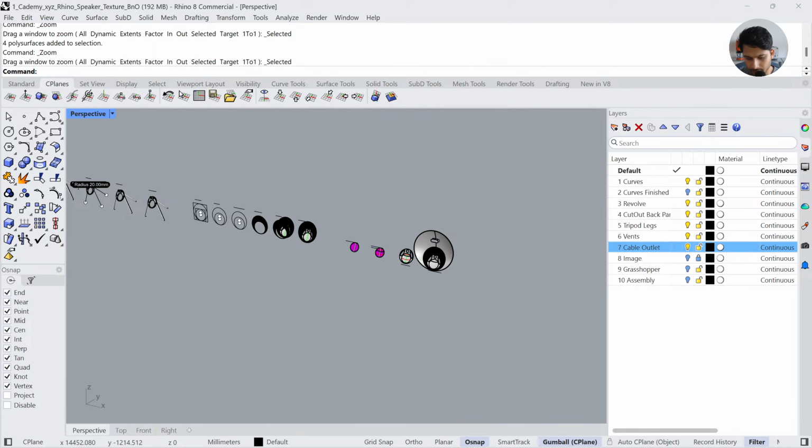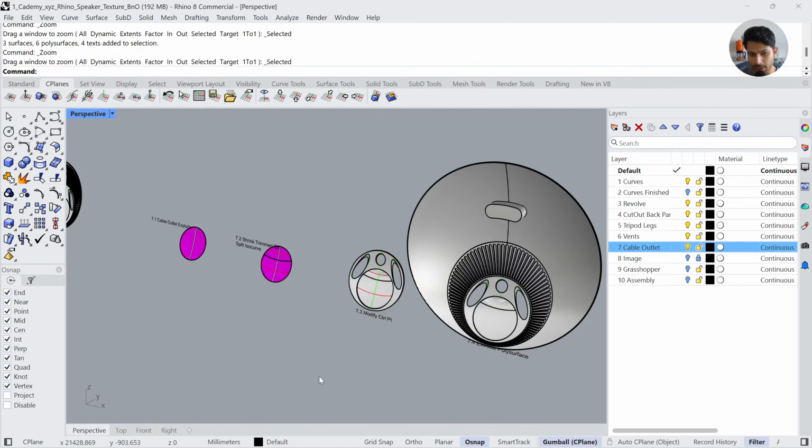Okay, is Rhino good for drone or airspace design? Sure, yeah, you can make some decent surface models in Rhino. There are certain drawbacks in Rhino compared to other primarily surface CAD modeling tools like Alias, right? So there will be specific steps that, for example, in Alias, you can do in one command, whereas in Rhino, you have to do the same steps in 3 or 4 commands, okay? And if this is a step that you need to do again and again, it can compound, which in some techniques of class A modeling is the case.